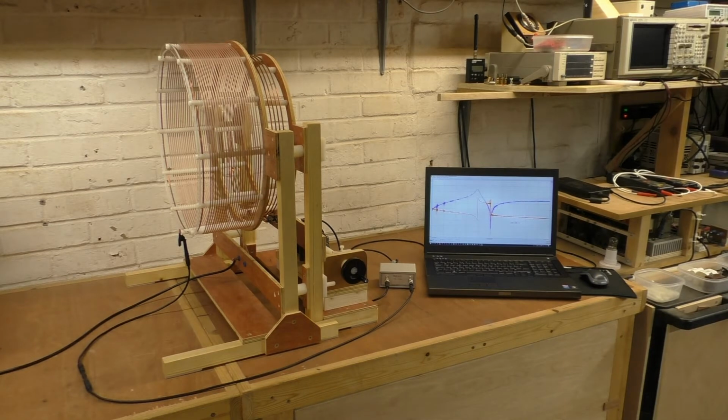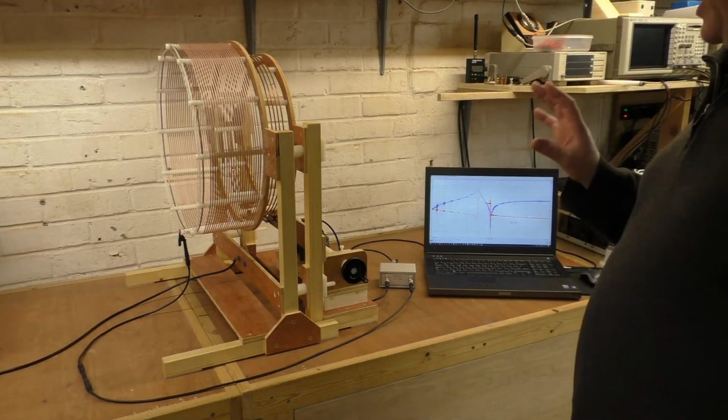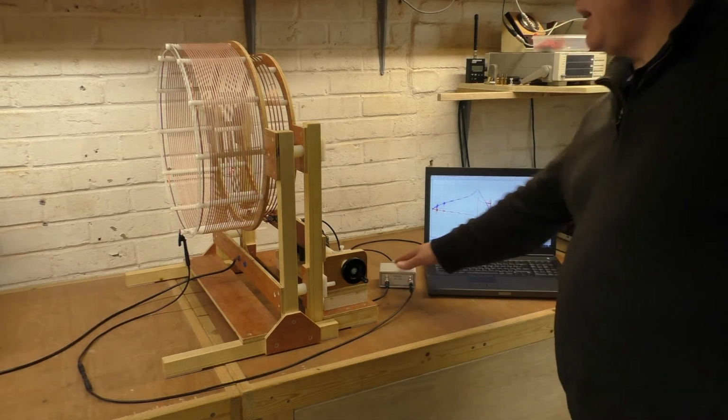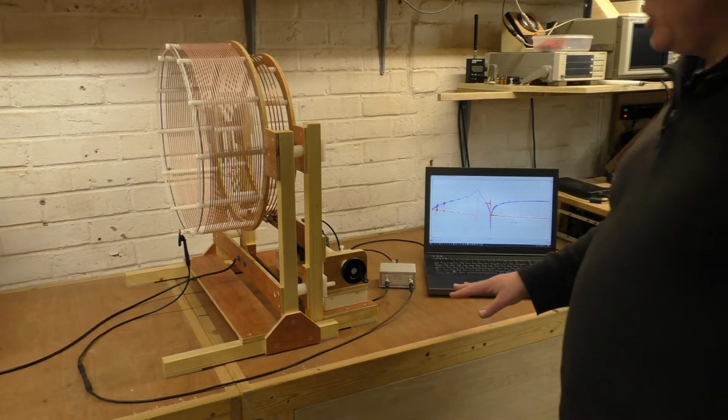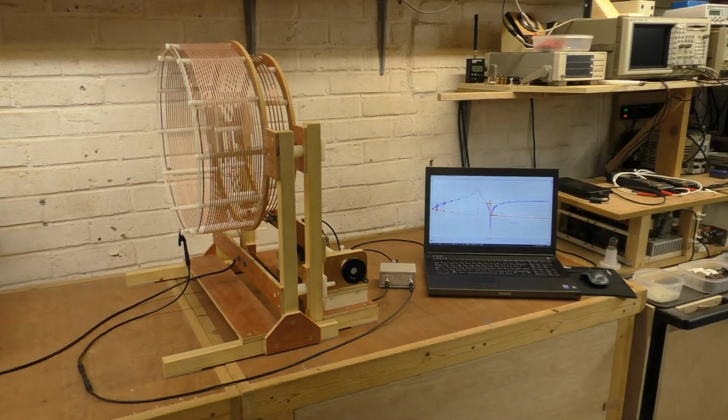So in this circuit, because it's a passive network, we are putting 0 dBm out. We know there is going to be an insertion loss, and we know that the power coming back to this port will be less than that. So according to those characteristics stated in the manual, we are within the acceptable range.